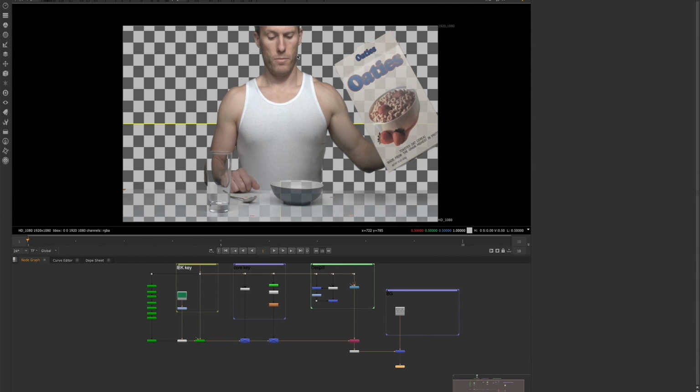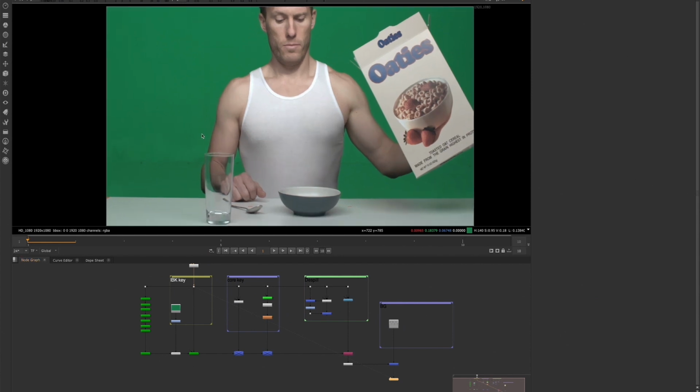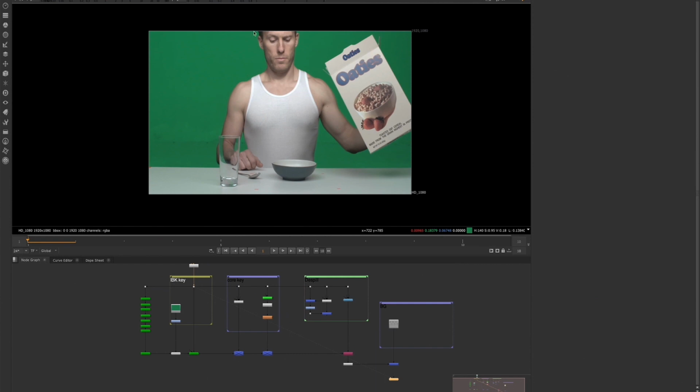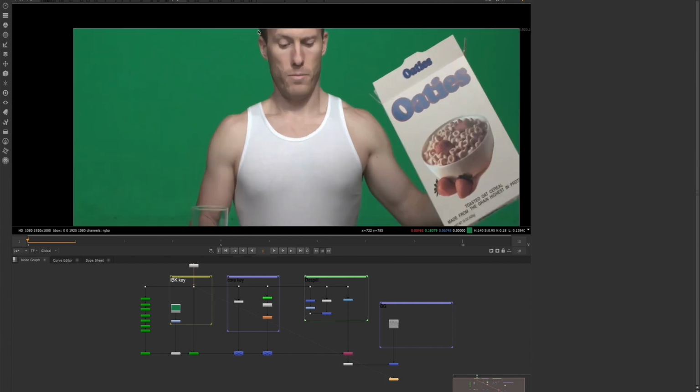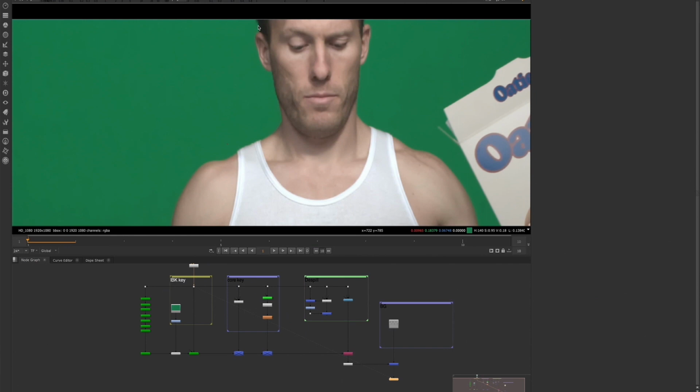So today we'll go over some of the keyers, the different keying tools that you have to use in Nuke when you're keying green screens. First, in terms of keying, I think it's important to know that when you're considering which keying tools to use and how you're going to break your key up, it's important to think of your keying in terms of, first, you want to pull an edge mat.